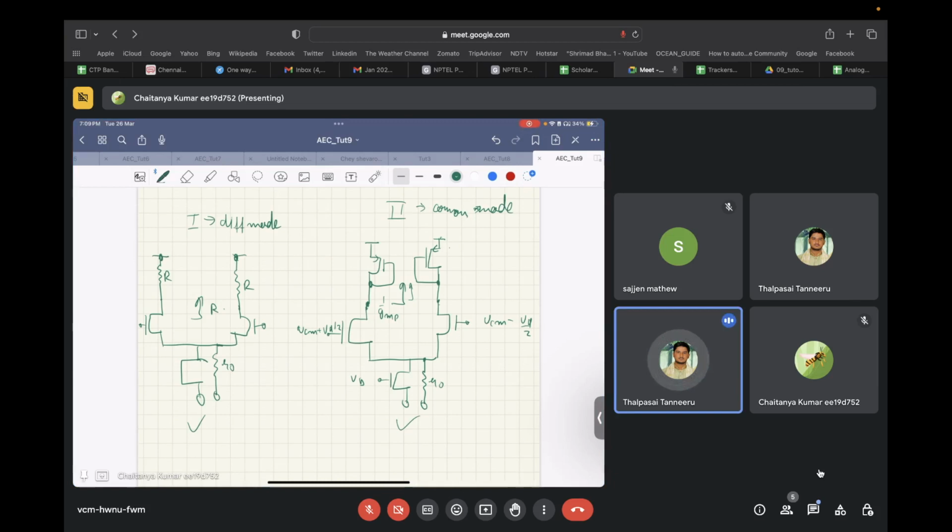Other way, you'll write small signal... No, no. See, for example, let's say this is some differential circuit, and these are two different halves of a differential circuit. If we connect two equal and opposite swinging nodes with each other, that particular node becomes a differential ground, right? Yes, sir. Okay.